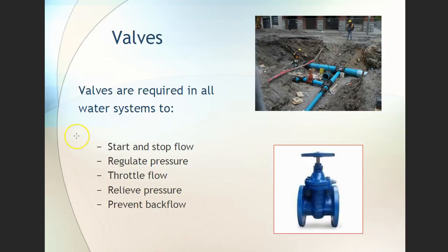Valves are required in all water systems to start and stop the flows, regulate the pressures, throttle the flows, relieve pressures, and prevent backflow. This is a gate valve. Again, gate valves are by far the most common.